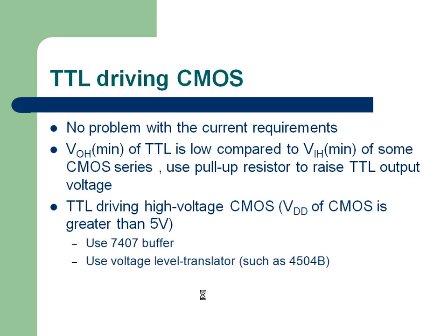Now see, we have a TTL gate. Let's assume CMOS. Sometimes not CMOS; in our case, it is a TTL. It's a gate which is producing an output voltage. What is the output voltage? We are concerned about VOH minimum. Isn't it? Look at our diagram.